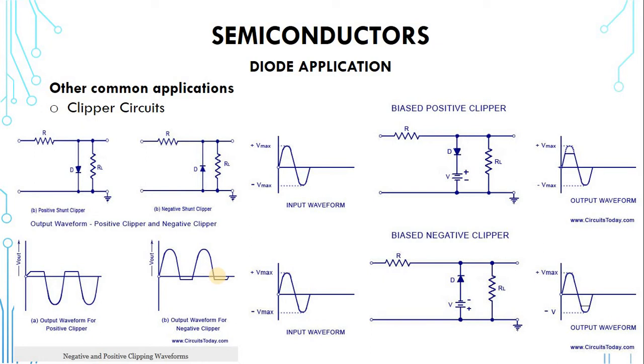Now in this circuit you can see that we are dealing with 0.7 because that is the forward voltage across the diode. But the question is, 0.7 is very small. Most circuits work with voltages beyond 0.7. So what happens when you need a greater voltage to clip? Because here you can see that if it's a positive clipper, it clips any voltage that's above 0.7.